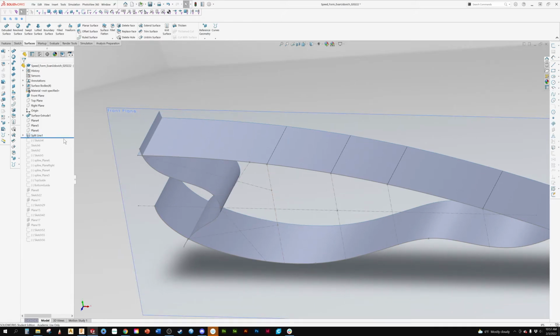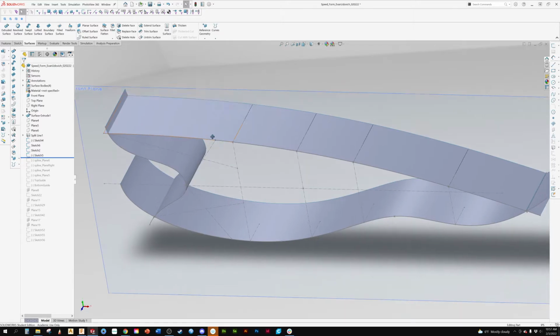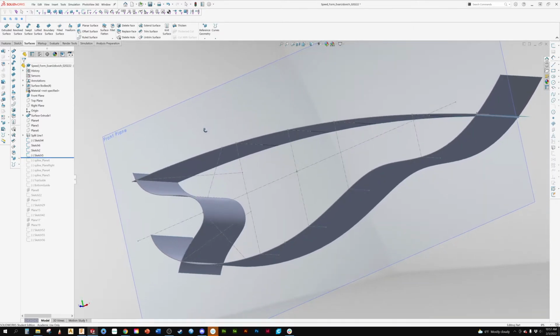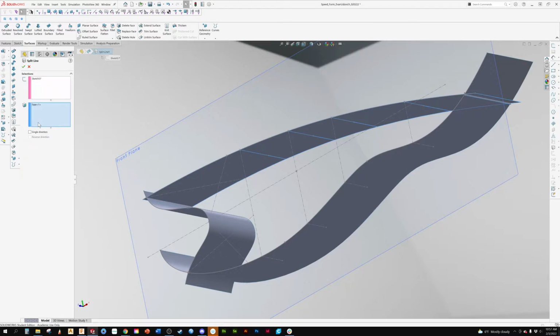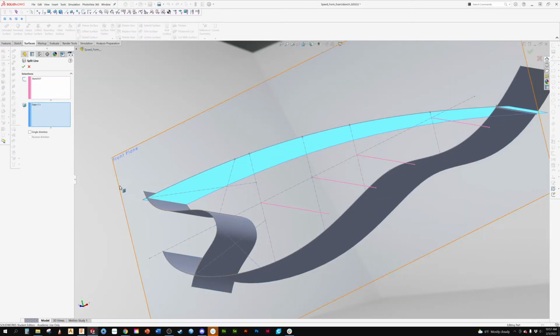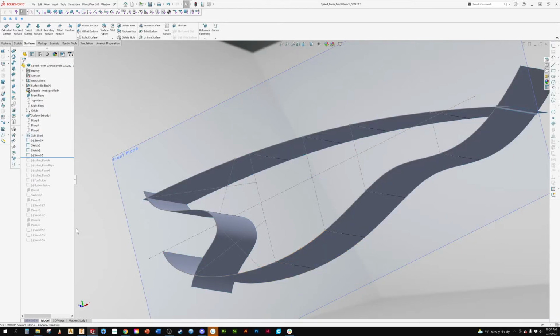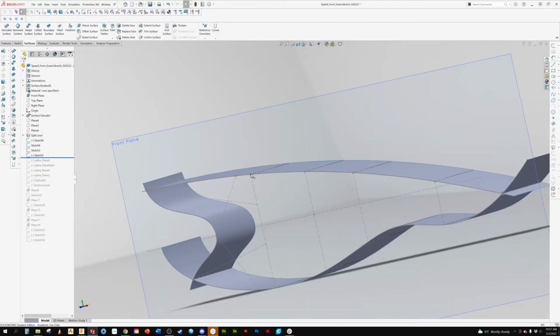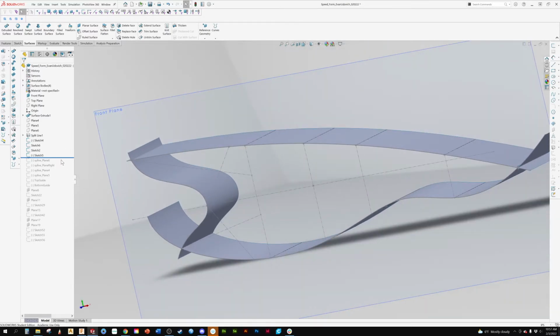So let us move forward here a few steps. I want to see where we can get those curves on there. And you can see here that I didn't put the split lines down here. That's fine, because we can just come back in our menu tree, and because those split lines are directly below, we're just going to select that face as well. Hit select. And now we've got the area for our curve points to snap to at the top and at the bottom.